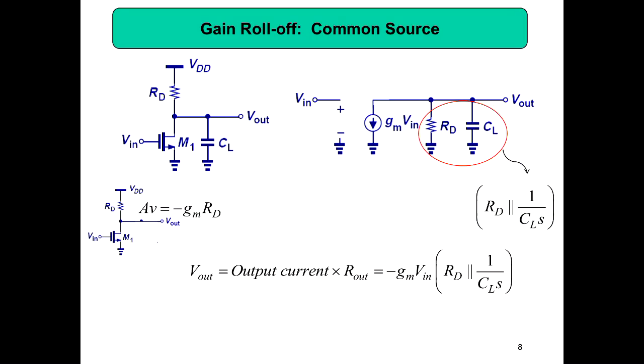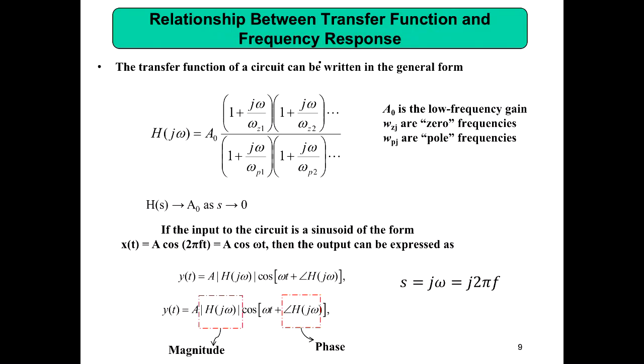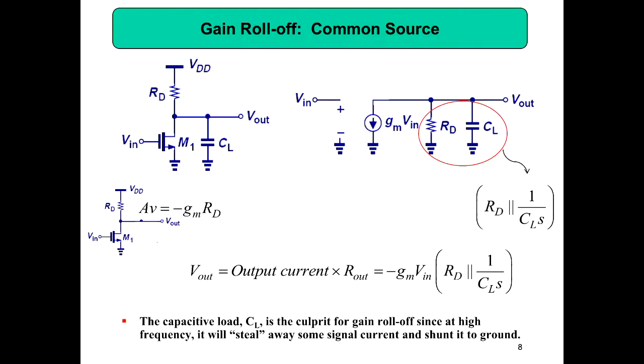Yes. At low frequencies, your capacitor is kind of open, so you don't have to take the capacitor into account. So that's called a low frequency gain. Then which capacitor? There are lots of capacitors in the transistor itself. Between base and emitter there is a capacitor, because you get a capacitor in a PN junction. Between collector and base, and between base and emitter, lots of capacitances are there. These capacitances we take as open. Why? Because at low frequencies that capacitance value is very small, so we take it as open.